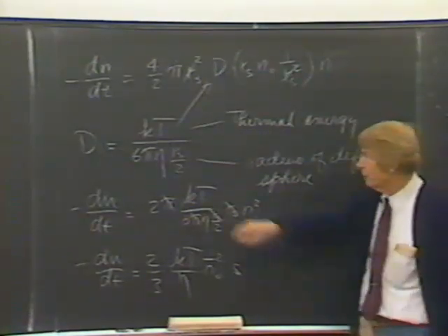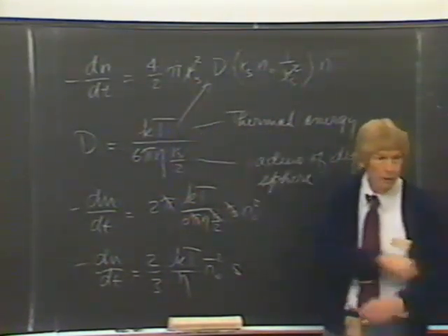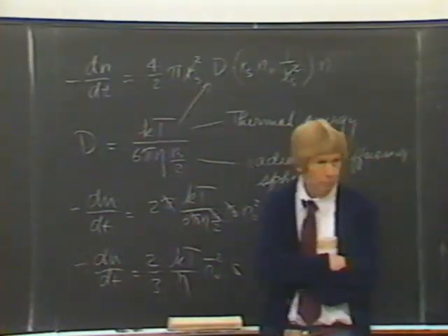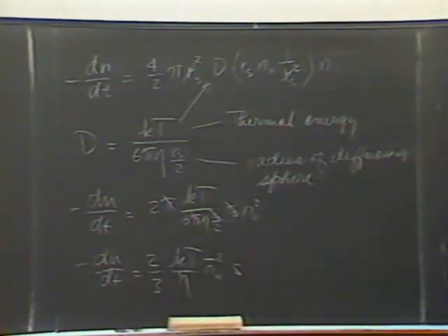Is there another limitation? I mean, is there a limitation at the other end, the lower concentration? At lower concentrations, the rate gets very slow. The example I gave you was for a 1 micron particle, that is 1 micron in length. It takes about 10 to the 12th particles per cubic centimeter. That's a lot of particles, 1 with 12 zeros after it, per cubic centimeter to have one collision on a particle per second.